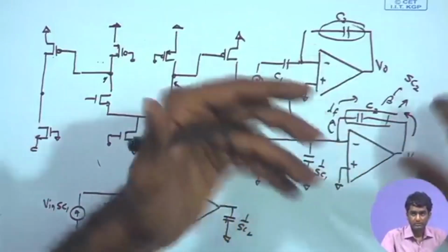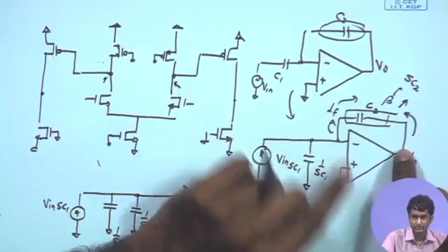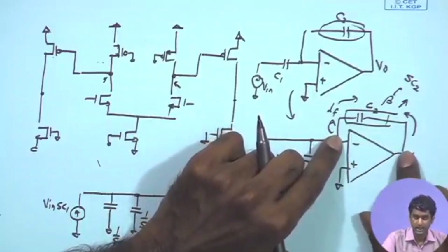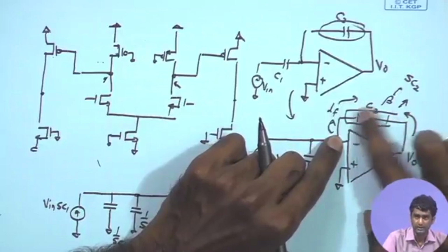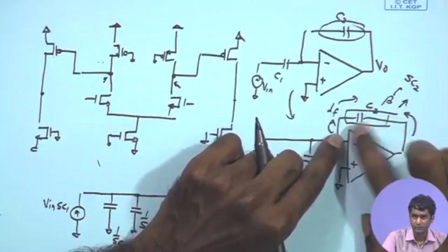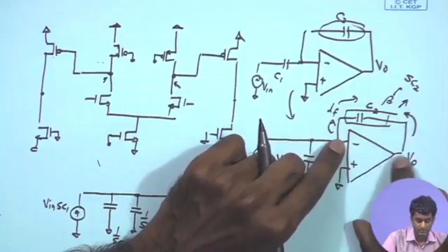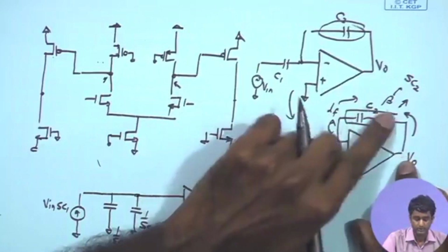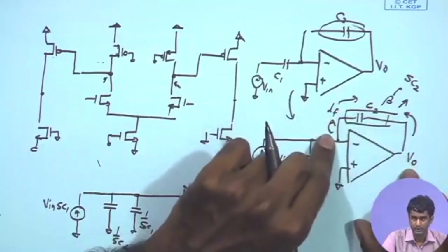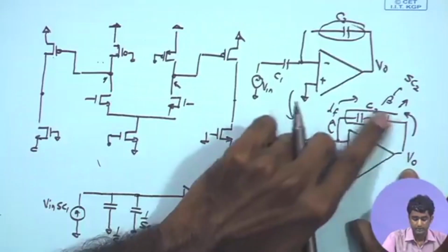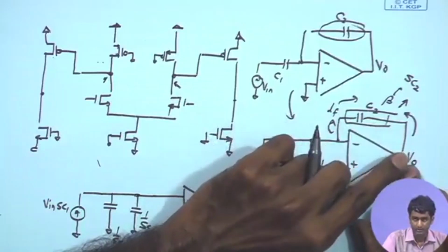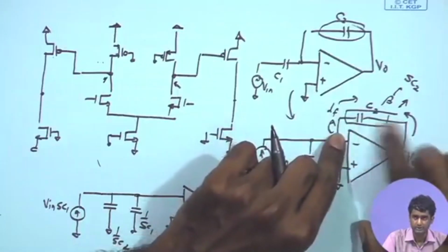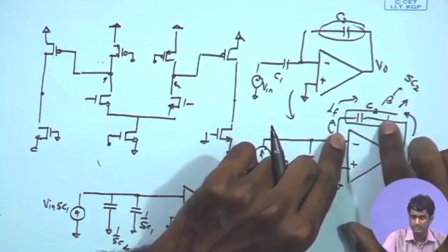Remember, in order to find the feedback factor for the shunt case, we need to put a ground at the output port of the feedback network, apply a voltage signal over here, and then see what is the resulting current. Why do we put a ground at the shunt connection? Because this is acting like a voltage to current converter. So, this feedback network is sensing voltage and providing you current. As a result, we are trying to estimate the voltage to current conversion gain or conversion factor for this voltage to current converter element.